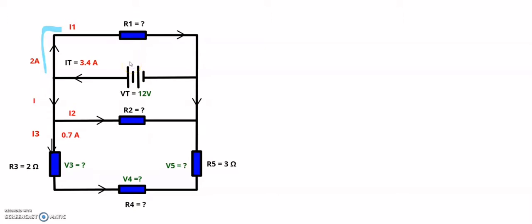The important thing of calculating this unknown resistor is you need to understand the theory behind the circuits. Otherwise, you will struggle to find a voltage drop over that specific resistor. The first thing that you need to do is have a look at where your resistor is positioned.